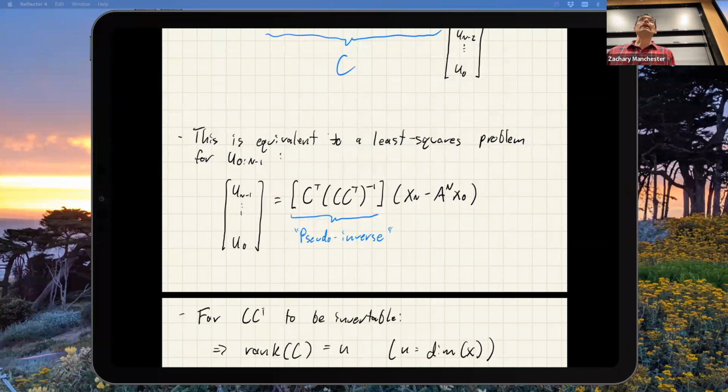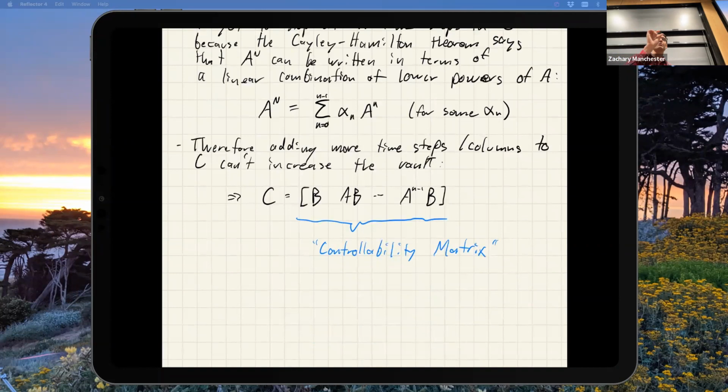Yeah, so this is okay for this version down here, where it's only up to the nth minus 1 power. As long as n is small-ish, like a small problem, like for a quad rotor or something, this is 12, this is fine. But for the time varying case, this is bad numerically. The actual answer is you should probably, in practice, if you actually want to compute something like this, just set up the QP and try to solve the QP. That's numerically better than trying to form this gramian thing.